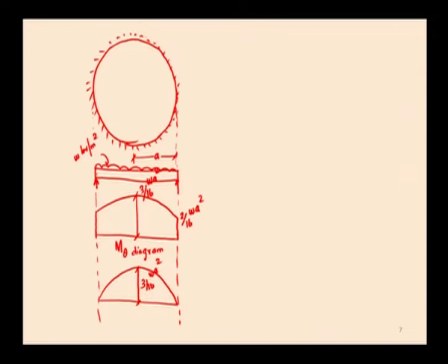Now, how to design the simply supported slab, the thickness of the slab as well as the area of reinforcement required. Here we have two moments, the circumferential moment and the radial moment. At the center they are almost equal, that is 3 by 16 W A squared. Both are positive, so we need to place the reinforcement at the bottom. Now, the reinforcement details.